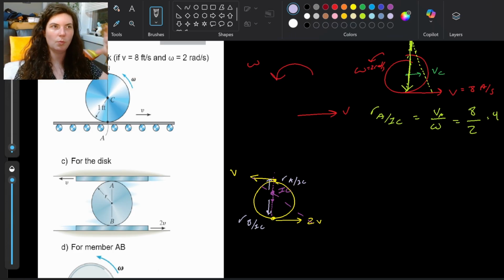So it's going to be somewhere in the middle of that disk, not at the center point, not at the centroid of the disk, but at the instantaneous center of zero velocity. So different than just the center. It ends up being a relationship between our angular velocity that we develop with those velocities and our r's to figure that out. So let me show you, if you wanted to find the actual value of where this IC is, how we would approach that.